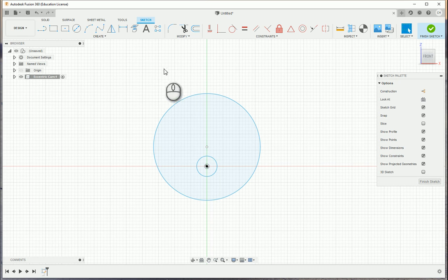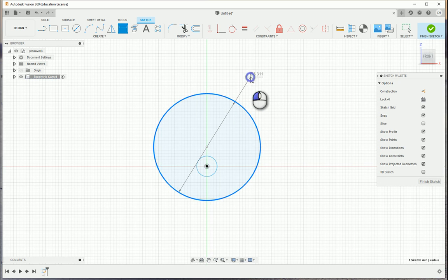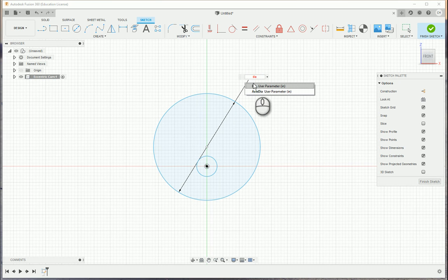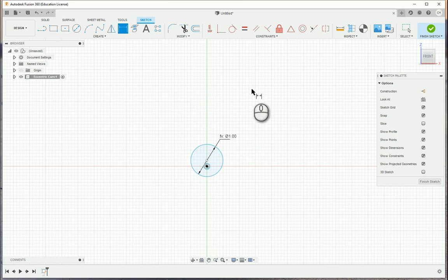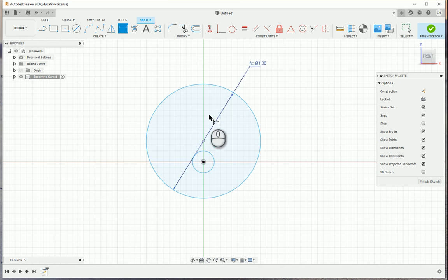So as I take a look at my dimension drawings that I have to work from, the outer circle here is going to represent the diameter. If I type DIA, or I can click on it and hit enter, that'll set that value in there. And then we can also have our hole diameter. So this will be axle diameter. Click to set in, hit enter.